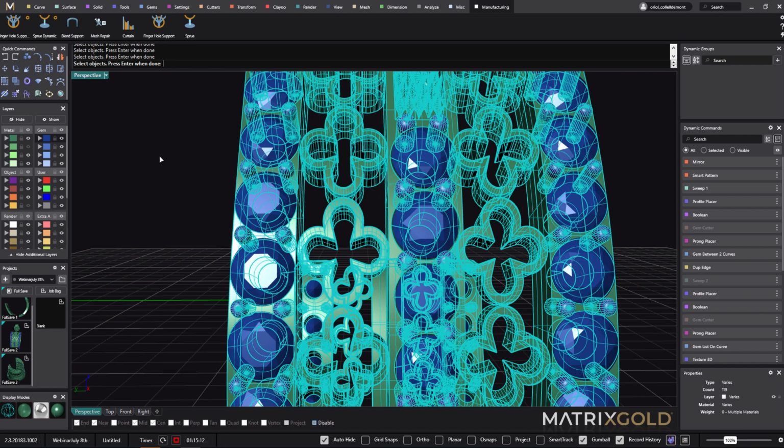So now what we are doing here is there are different steps when we are using the mesh repair. The first step is we are just bringing all these parts to mesh, and you will see now, with the different parameters that we have, you can set up what resolution you want for this mesh. And then you also have the output that you want to get from that mesh. So you have two different settings that you can play with to get the right definition, all right?